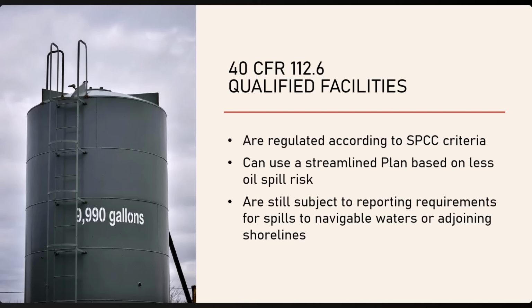less expensive to develop and maintain. However, if the amount of oil storage increases or spills occur, then the switch to a full plan might be required. Lastly, qualified facilities that cause a spill to navigable waters must still report the incident in a timely manner to the EPA or possibly to state agencies. There is no leniency for the spill reporting requirements. As stated before, a spill can invalidate the qualified facility status.